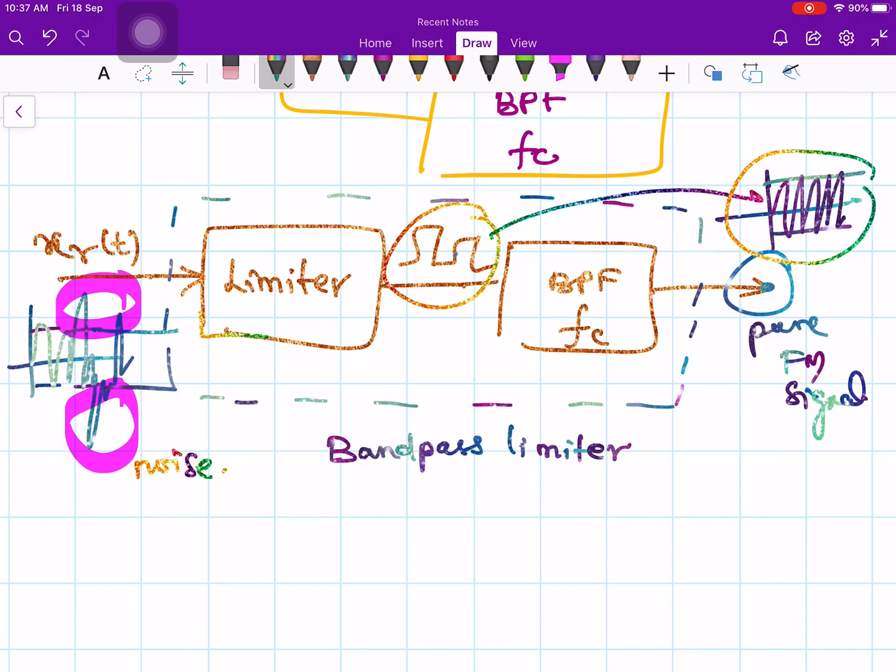So the amplitude variations are killed by this amplitude limiter. You can look at this: this cycle has large amplitude, and here also I have large amplitude, and here also. These large amplitudes are removed by the limiter. Maybe look at here, this has smaller amplitude. So whether it has a larger or smaller amplitude doesn't matter, it produces a constant amplitude frequency modulated signal, and all these variations disappear once you have the hard limiting operation. That was the reason we put the limiter.